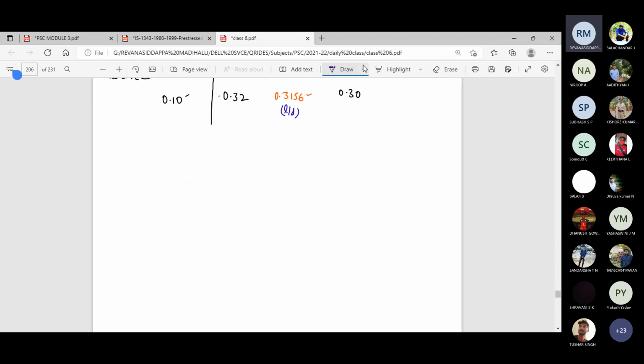XU by D is equal to, therefore, let me take that value, 0.228. XU by D is equal to 0.228, with D being 1800. You can calculate the value of depth of neutral axis now. If you calculate, it is 410.4 mm.